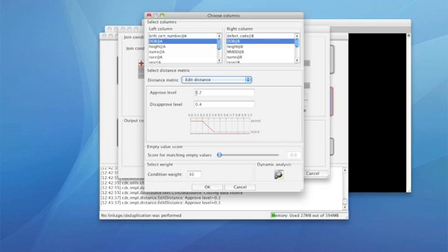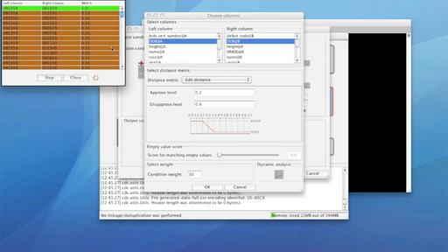What we want to do is allow in this edit distance just one edit between two dates. So basically, when two dates are exactly the same, we want the value of the distance metric to be 1. When the two dates are off by one digit, we want the value to be close to 0.5, and otherwise we want the value to be 0. What I'm going to do is open the dynamic analysis window again, play with the attributes here, and set the values to 0.05 and 0.2.